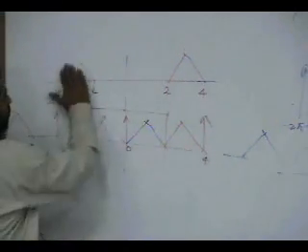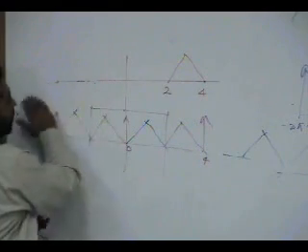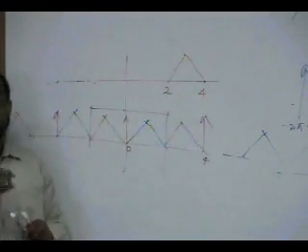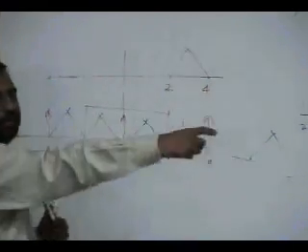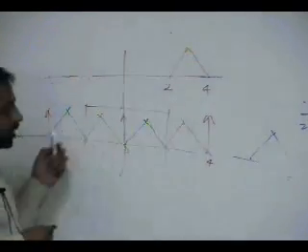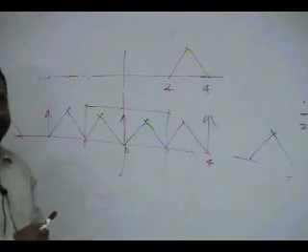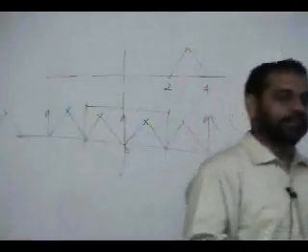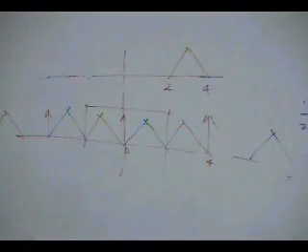Usually we do this as well. You say, I'll make this I and Q, I'll make it complex. Complex means the spectrum is only on one side. If this is on one side, then you can bring it down by again doing some aliasing. You can even bring it to 0. You can think to bring this whole thing to 0.